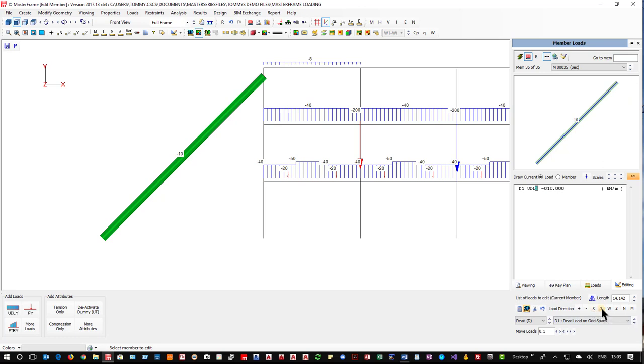So that's your basic load directions. The W is this weight, this self-weight, which is very useful for dead loads on sloping members. Personally, I would never use it unless your members are at a slope of greater than about 7-8 degrees, because less than that you're under 1% variation in load. Obviously density we handle separately, and they're always measured per linear meter of member.